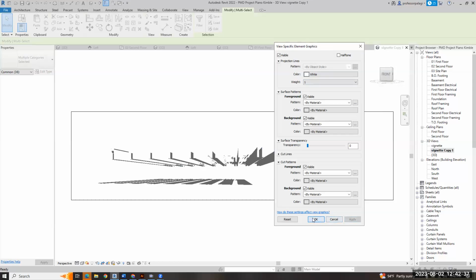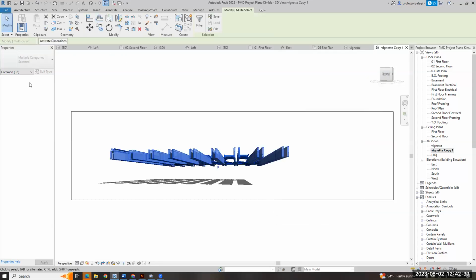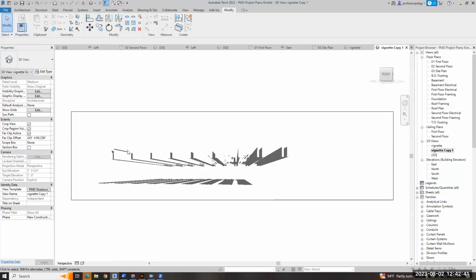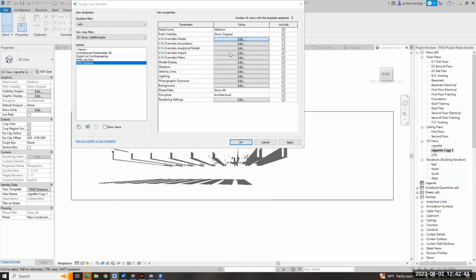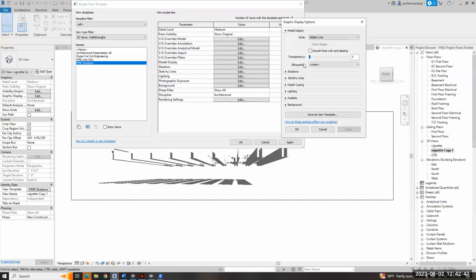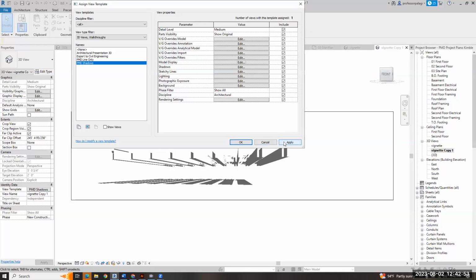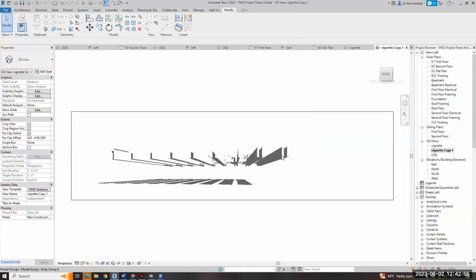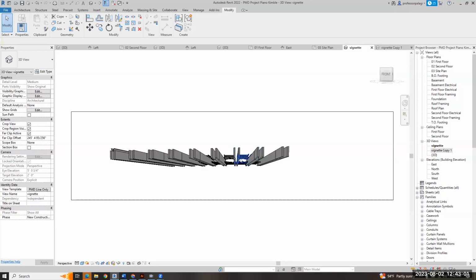Apply, and I make sure that there's no profile edge, which means you got to make sure in that setting there's not the extra, because you'll still get the line if you've got the silhouette on, because that didn't change. The silhouette's kind of like above and beyond the graphic of the object. So I had this view saved with the line view, and that's what I exported to get the running.